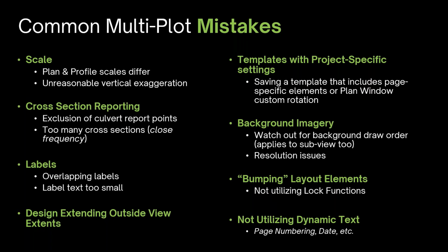We've got templates, and as I showed you, we can save our book template or our chapter template. But if you've set something up to be on a page-specific view or having some really project-specific settings, just be aware that when you're saving those templates, they are going to be highlighted inside of the multi-plot with some different annotation in the corners. So either a green triangle to say that it's page-specific. So those are things to watch out for.